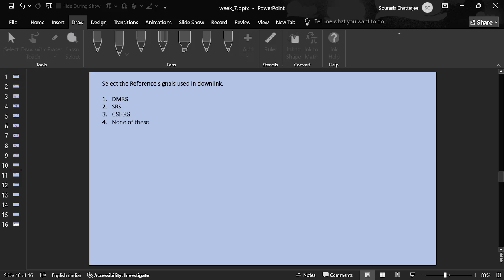Fine. And what is the purpose? Link channel condition. So basically you are saying that SRS is being transmitted from the user end. It's like a pilot, the user transmits these pilots, and the base station estimates the channel, the uplink channel, of course. Fine. Once the base station has the uplink channel, it can use it in the downlink, so that it can achieve the MIMO gain. Good enough.